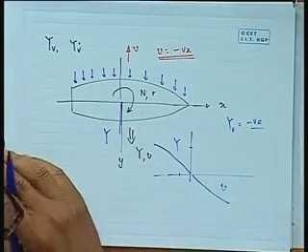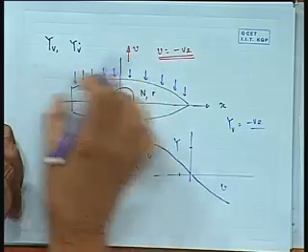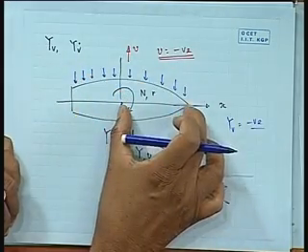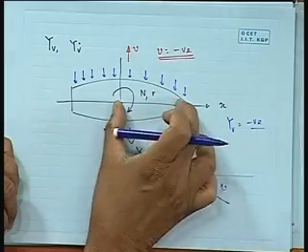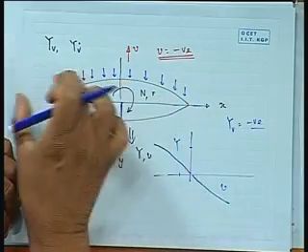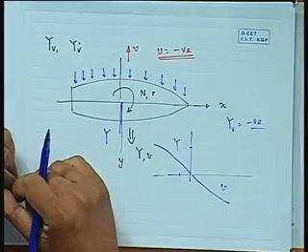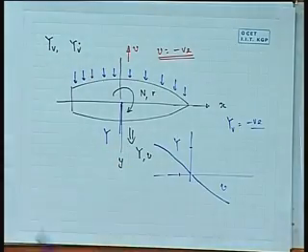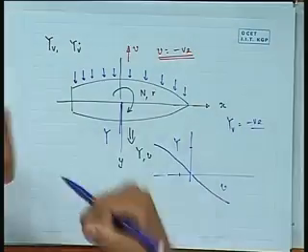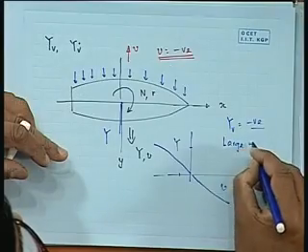That is one. Therefore, yv is negative, no question about it. Is it large or small? Question is that here at every point, let us call this the stern region, this the stem region, forward region, aft region. In the entire forward and aft part my force is acting in one direction. The entire fluid is trying to push it on one side. So what happens? It becomes a large negative.